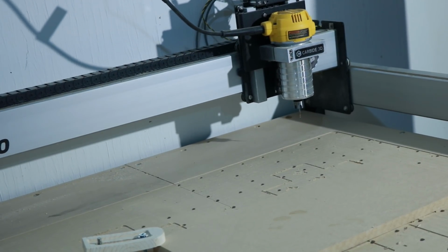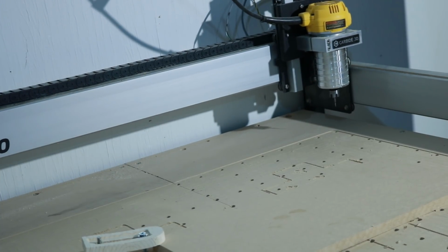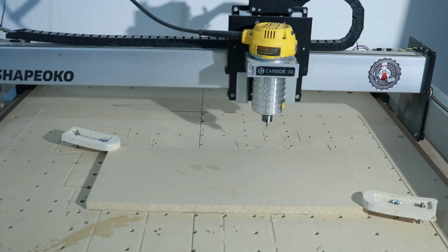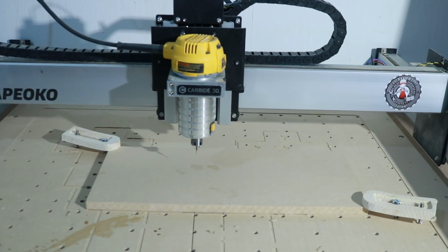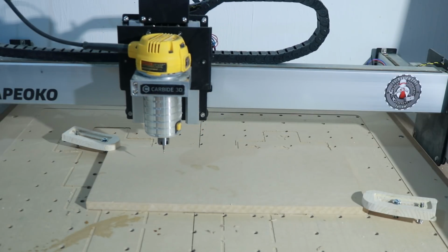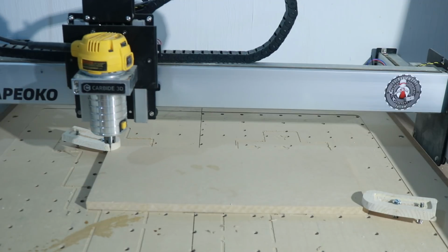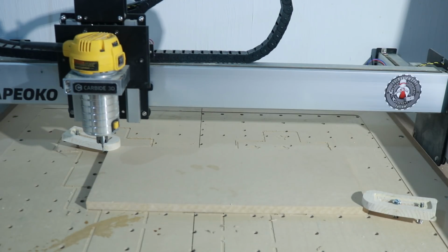Now once it homes, that's where you're going to be able to come over and zero this out right here. So now all we're doing is we're bringing this out. We hit a rapid motion, and we just have to zero this. So we're going to bring this over. We're going to put this on fast. And I am going to have a separate Carbide Motion tutorial coming up soon. We're going to bring this over down to that lower left corner, just like we set it up in the Carbide Create.